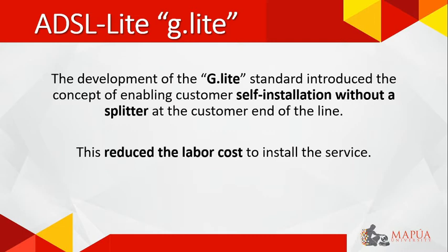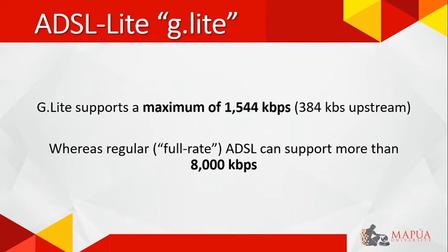Field trials of G.lite demonstrated that an inline filter must be inserted in series with most types of telephone sets to prevent problems for both the voice transmission as well as the digital transmission. Subsequently, it was determined that an inline filter permitted effective operation of full-rate ADSL, whereas G.lite is restricted to about 1.5 Mbps downstream. As a result, the large majority of current ADSL installations use full-rate ADSL, self-installed by the customer, placing an inline filter by every telephone in their premises.